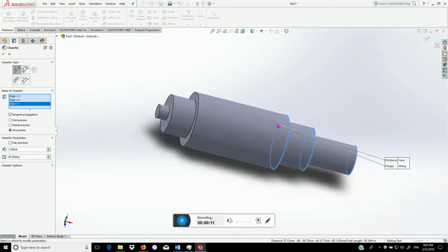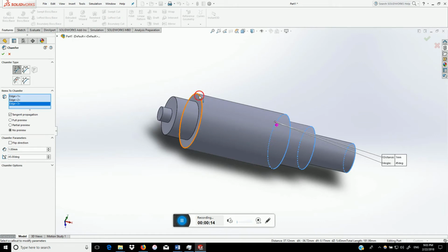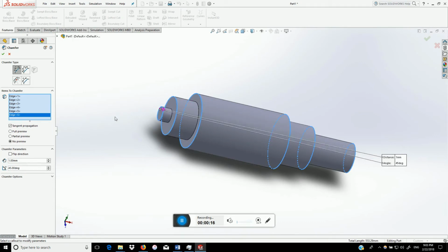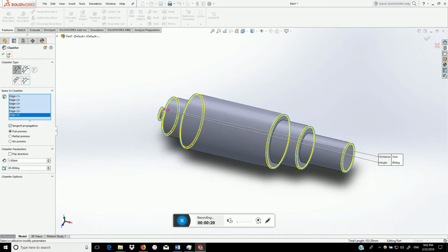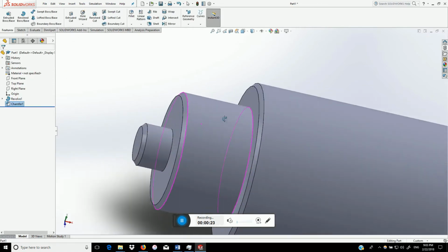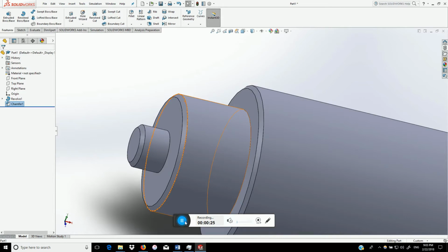accommodate. It can only manifest if it can be previewed. Also know that unless you hit the multiple radius option, all the fillets and chamfers will have the same size. 1 mm times 45 degrees is more than enough for human scale operations.